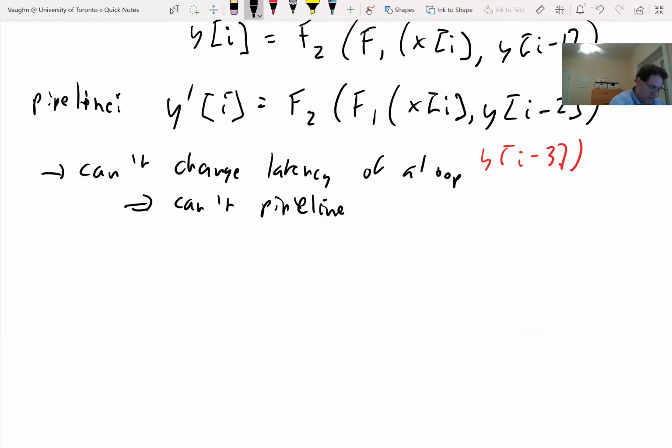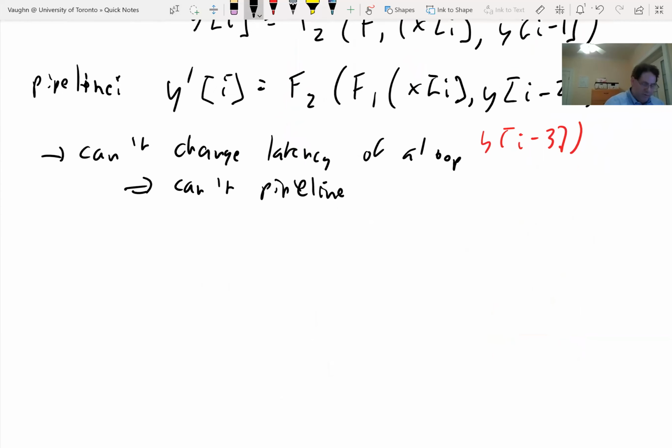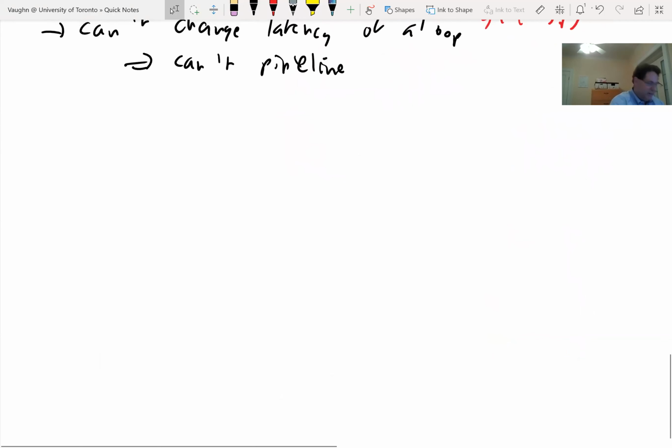That was a bunch of discussion about a very important optimization, pipelining. And again, it's because it's the most hardware-friendly form of parallelism. You just add registers, you don't add anything else, and you have multiple pipe stages working on different parts of the computation. The state's distributed. So you generally in hardware designs try to fully exploit as much pipelining as you can before you start looking for other forms of parallelism like replicating functional units.